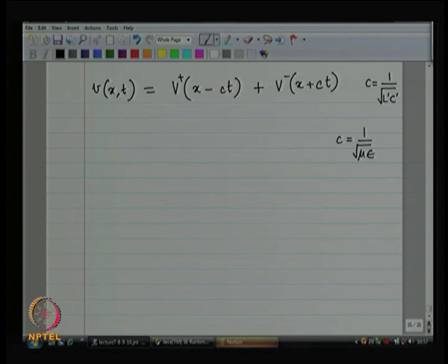Typically, this is what you are going to get as the speed of the wave. Which tells you that if you happen to know the inductance per unit length, you can easily compute the capacitance per unit length without doing detailed derivations. But anyway, we did two different geometries, and then we did some hand waving, and then we said that the product of L and C is going to be a constant, etc. This is actually the reason why the product is going to be a constant. It is the speed of light in that particular material.